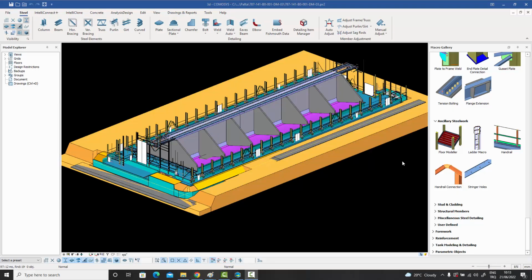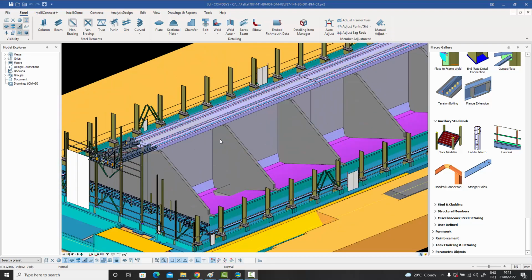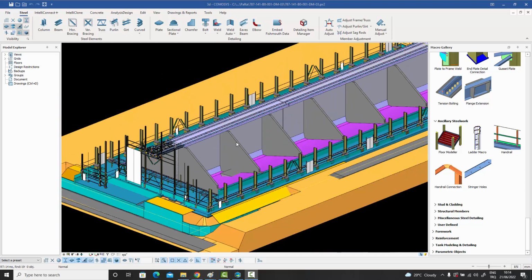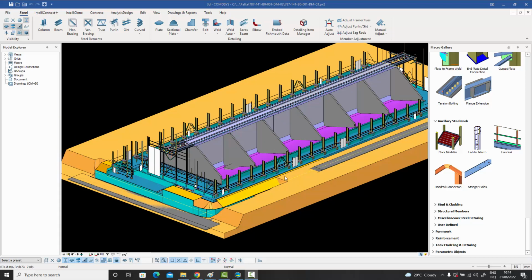Now, if you remember, I had said that there are 5 types of objects which are merged together on the drawing side. There is the cast in place group, the precast group, the plain concrete group, the grout, and earth, which is for modeling the excavation. So I want to give an example for the earth one. Over here, there's this complicated structure from a cement plant, and around it, the detailer has modeled the soil. So this orange thing you see around it is basically the soil.